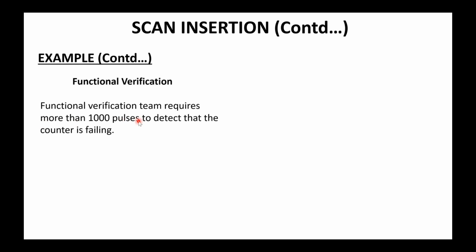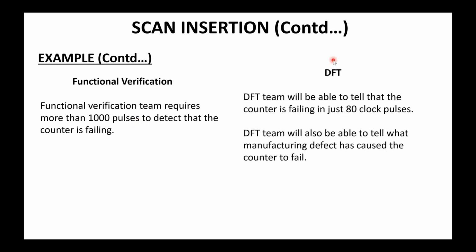The same thing, as a DFT engineer, we are not going to check the functionality, and as we have also gone for scan insertion, we can tell that the counter is failing in just 80 clock pulses, or within 100 clock pulses.